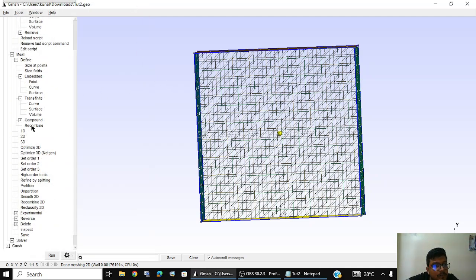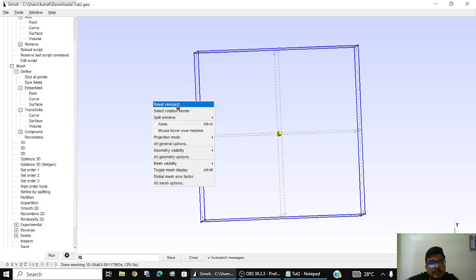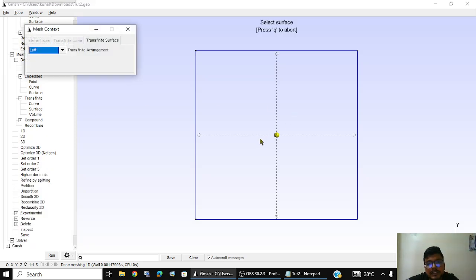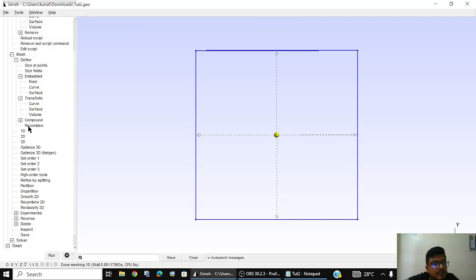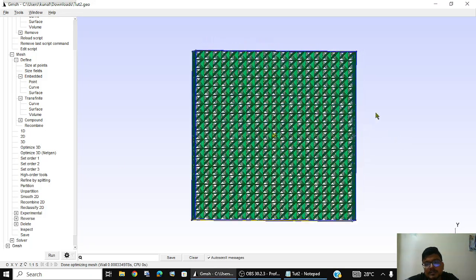We'll just cross it off and then again. So it is in the same mode. Again, we'll just try to change it into alternated. So transfinite surface, selecting a surface. Okay, marking it alternated, and then E, and then Q. Reload the script. Then 2D, then you are done. So alternated meaning you are having both on lines, diagonally both on lines. Okay, 3D.